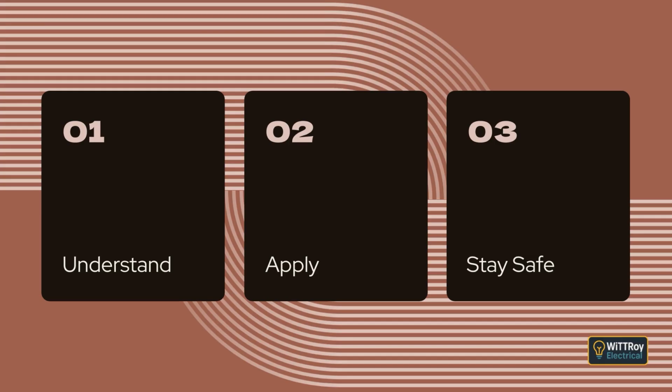Clause 2.5.5.2 Reduction of the probability of the initiation of a switchboard internal arcing fault. This clause explains how separation inside the switchboard reduces the chance of an arc starting. Heavy current switchboards must have internal separation to at least the level described in the switchboard standards. This separation applies between bus bars and functional units, functional units from each other, terminals for external conductors, and in some cases, a safety service section. The general idea is that by physically separating parts, a fault in one part is less likely to spread or initiate an arc elsewhere.